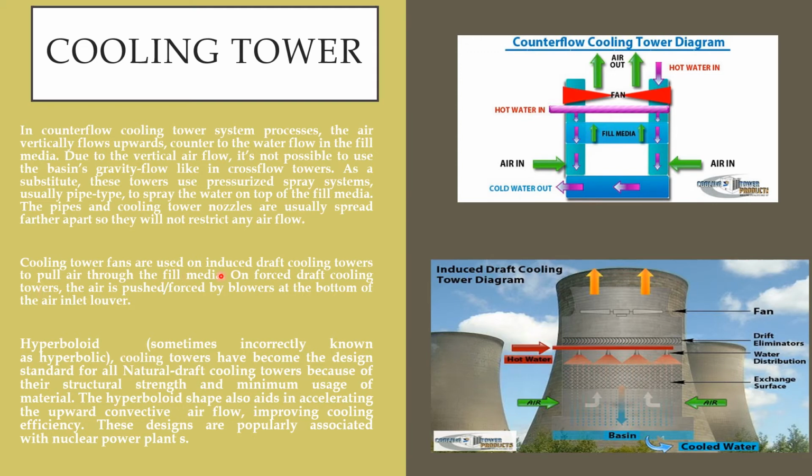Cooling tower fans are used on induced draft cooling towers to pull air through the fill media. On forced draft cooling towers, the air is pushed or forced by the blowers at the bottom of the air inlet. The fan will be here.